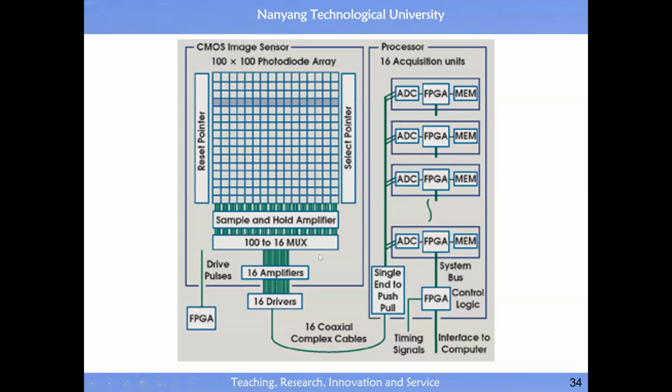Then this is an example of a MIMO channel. Because this is a multiple input, you see, you have multiple ADC, so multiple output. So it's a MIMO system, all right? It's very important because not many people use this term, MIMO, MISO, SISO. But actually, this term helps you to understand the nature of signal flow inside a complex system.